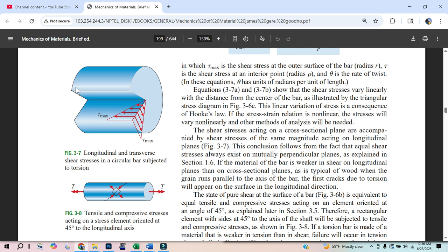Now, that's at the surface because that's what we're observing. I'm observing this angle, and I'm using this radius. At any point, I could have just said, well, let's not use the radius, and I want to know this. I want to know that this sweeps out an arc length. Well, at the halfway point, what's the arc length that it sweeps out? It's still the angle of twist times, and then divided by 360, that's the proportion of the circle. And then this little circle has a circumference of 2 pi r. So you could do that.